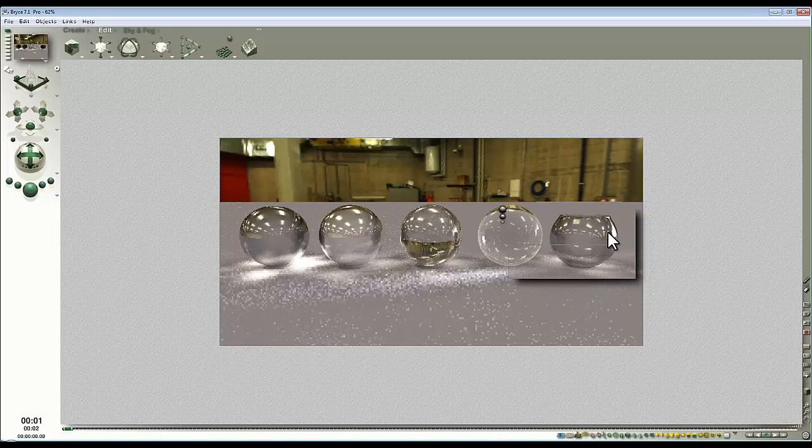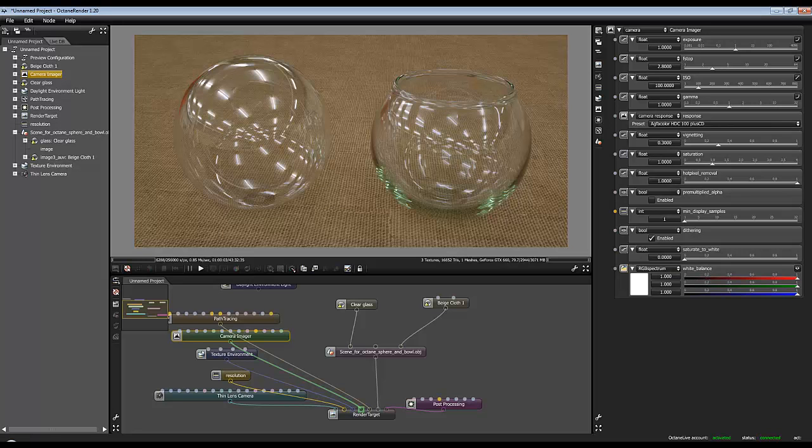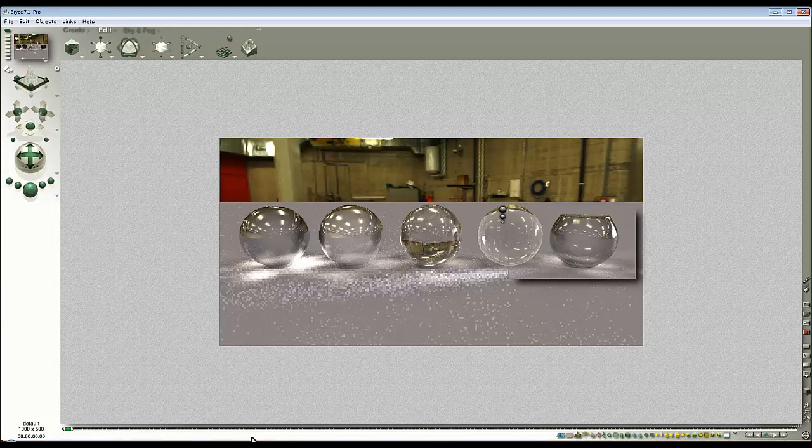So this has lightened the glass now, you can see that, and I think that's looking more like the glass we're seeing in these images, even though its refractive index isn't exactly correct. In the background I've been rendering away with Octane to see what it makes of this challenge using its glass properties, but that's another story. This is looking a bit dark, and I've not even used the effect, because I've got grazing angle built into the transparency. I don't really need to use the metallicity to reduce the effective reflection where it's facing the camera. What I could do is I could make it a little bit less transparent, or give it a colour to tint the colour of the glass as appropriate.